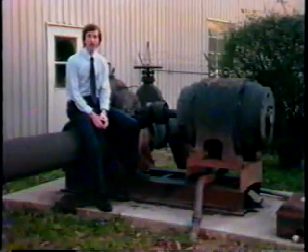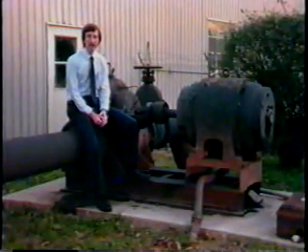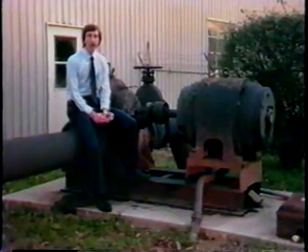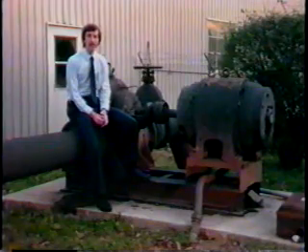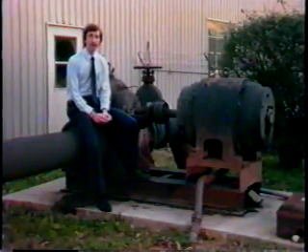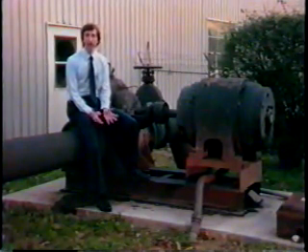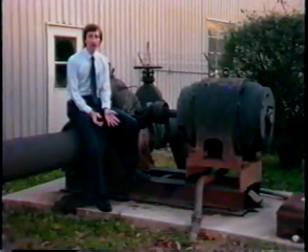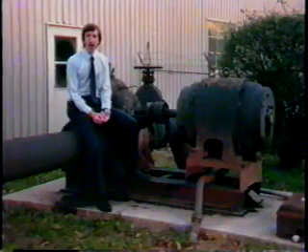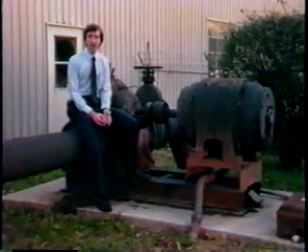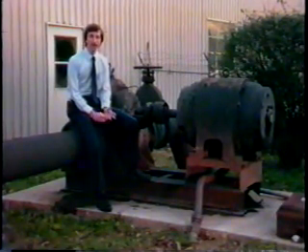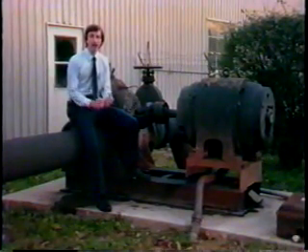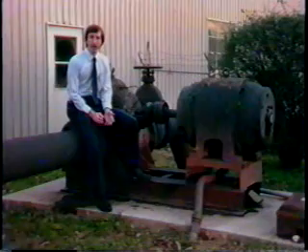You're wondering why I'm leaning up against this pump when we're really talking about hydrant flow tests today. Well, as you know, what's happening at pumping stations has a lot to do with the resultant tests. Yet you can look at the results of hydrant tests run by some people and there's no indication of whether pumps were on or how many pumps are on or which pumps were on. This is unfortunate because it renders the results of these tests less useful for calibrating pipe network models.